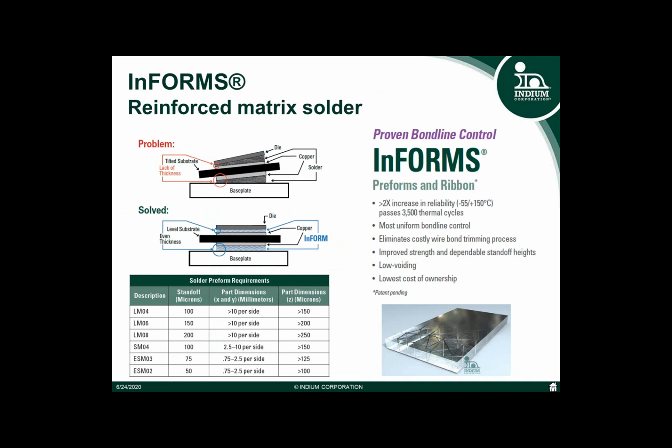This, of course, then allows for improved thermal transfer, but we are also able to prove that against the use of a standard preform or a standard solder paste, where the tilt could be an issue in production, we have minimum 2 times the reliability in most thermal cycle cases.